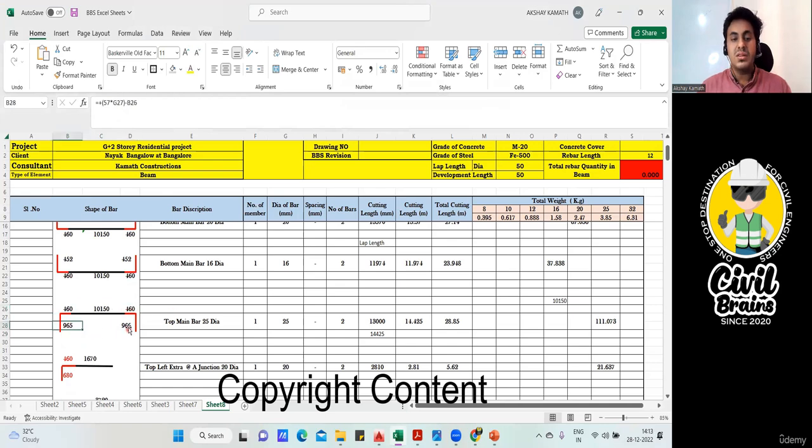What about this length? This length is very simple. It is a completely development length. I'll show in this way. This is completely development length from here to here. So bar is like this. Yeah, so this is completely development length. This length I already got, 460. And this overall is 57 into D. From this 57 into D, if I deduct this 460, I'm going to get this vertical.